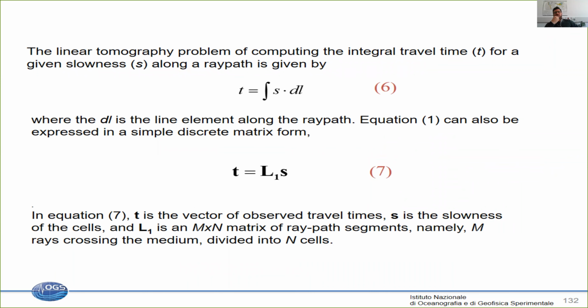So we try to solve the problem as a standard linear tomography problem, exactly the same as we have seen in the inversion procedure. The travel time for each path between the two sensors is simply the sum of the propagation along the line in each hypothetical block, like we have seen last time, multiplied by the slowness in the block. And then I sum up for all the different paths in each block.